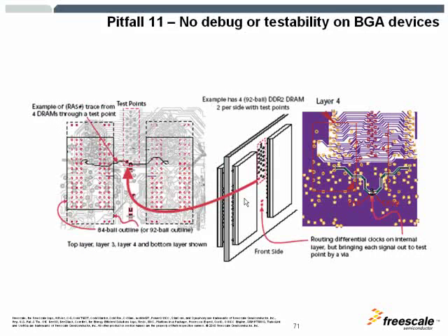Also, an important piece of information to note: if you're soldering your DRAMs on the board and you're doing your own layout, make sure you bring out the signals, because all the DDR2 and DDR3 parts are BGA, and there's not going to be any access to reading the signals when you want to troubleshoot.